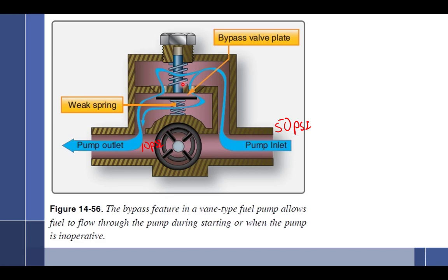Well, yours is different. It will still work going this way, but it won't work going this way. We can even just look at it and say, as long as this 50 is greater than this, it can't push it up, because that 50 is going to be pushing here and pushing here. So that's going to create a problem. And honestly, the pump you guys are working with is the same way. It's got a very large surface area. So as long as the boost pump is exceeding the engine-driven pump, it's going to stay down. It just has to.